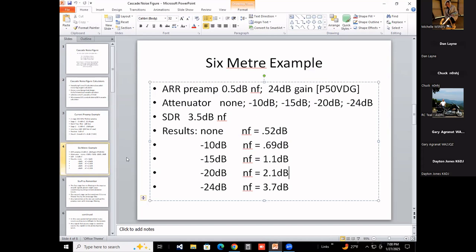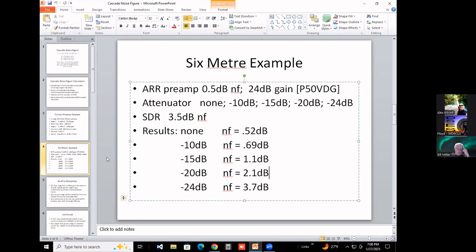Yeah, I just want to comment on what Case said about the SDR and 10 dB pad and the noise figure. Well, the golden rule is the more gain you have, the more noise. You can't just get rid of that physics. But if the SDR is set to maximize gain, and you have an auto gain setting, you're actually compromising your overall noise figure.